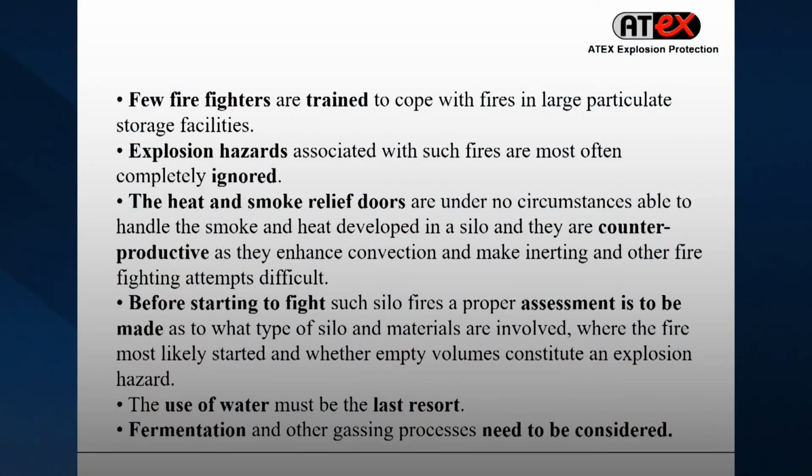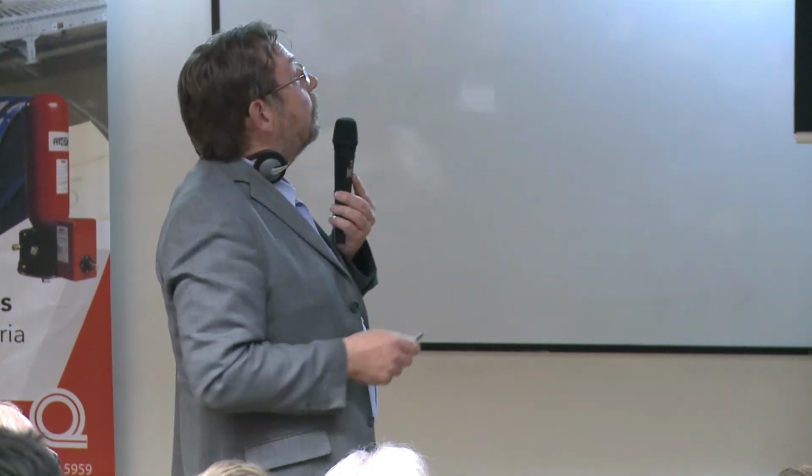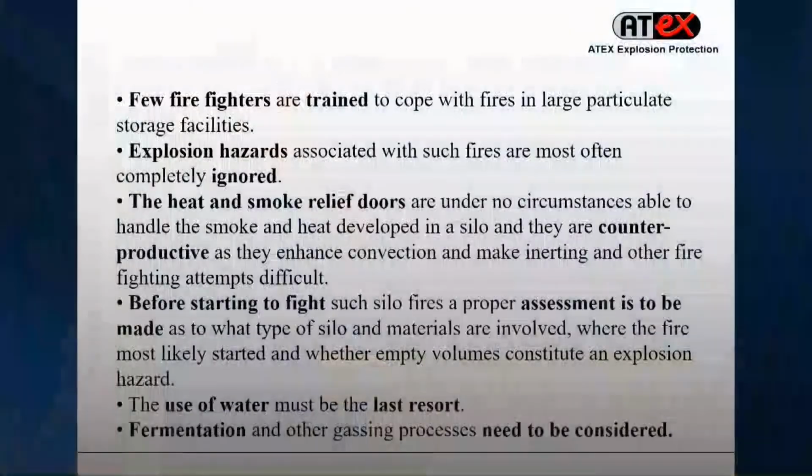And before starting to fight such a silo fire, an assessment is to be made. Where is the fire and how did it start? So that you do not bring the fire into all the material. It would have been much, much easier to fight the surface fire if it had been done the right way. But in this case, it was not possible. And then, of course, the use of water must be the very last resort.